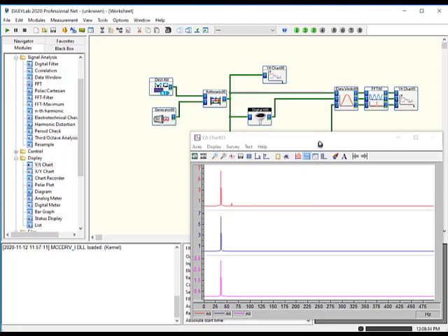So that just compared a filter function and an average function. Depending on the data that you're looking at, if this were temperature data, this would be perfectly suitable. For vibration data or audio data, you might not want the filter to damp out so much amplitude.